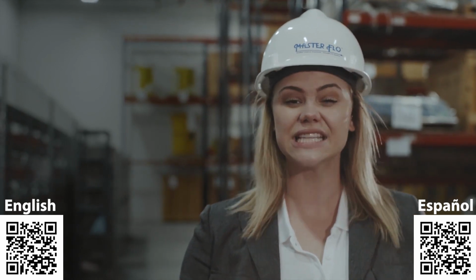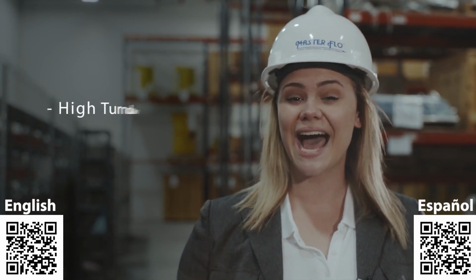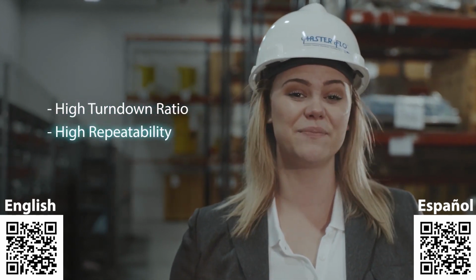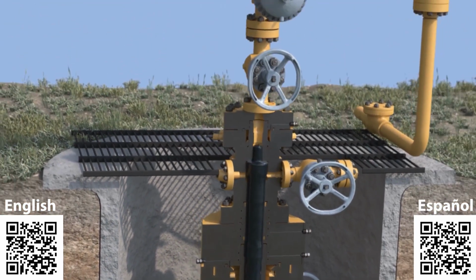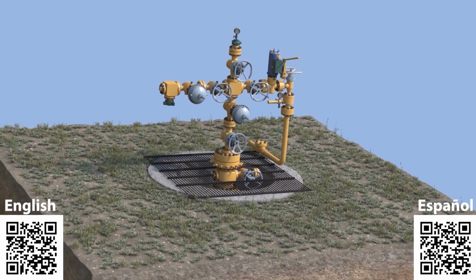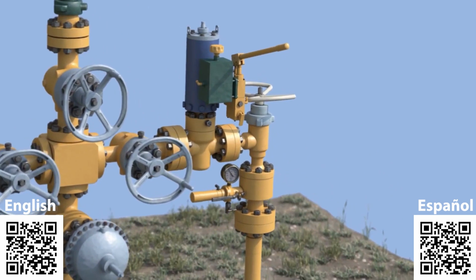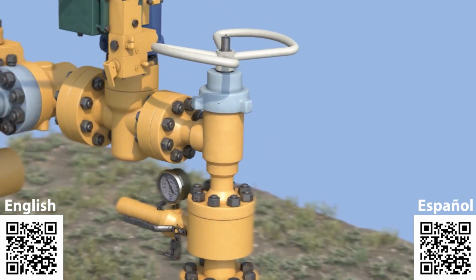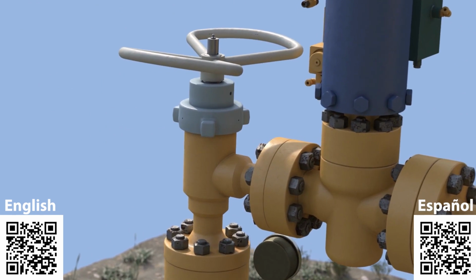This brings the well on stream. As the valve is opened and the flow increases, this level of control is maintained throughout the stem travel, resulting in high turn-down ratio, high repeatability, and precise flow control. This is imperative because a well-controlled flow allows you to ramp up your well slowly. A rapid well ramp-up can destabilize it, potentially causing a collapse and reducing the well's productivity index. Avoiding damage to your most valuable asset, the reservoir, is crucial.